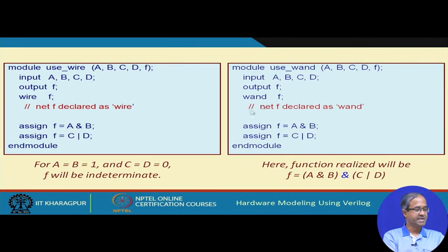These are all operators which have a direct correspondence with the hardware. So, in hardware we have this concept of wired AND and wired OR connections. Depending on the logic family, if you tie the output of two gates together, for example, for CMOS it works like a wired AND. If you connect the outputs of two CMOS gates together, the output will be 0 if any one of them is 0. That is how it works.